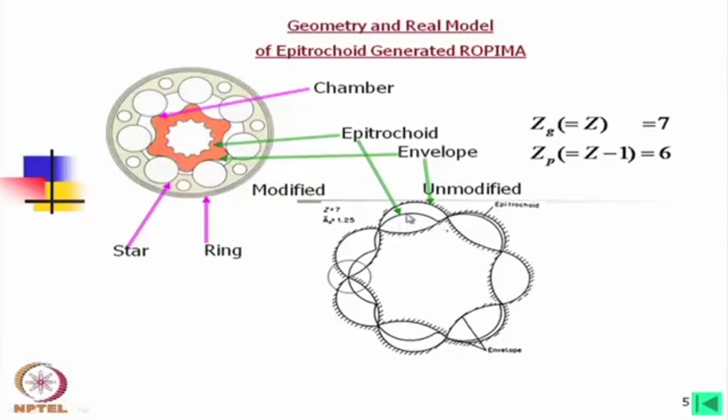How? If we make this one a solid cutter, then we will find it will make a profile like this, which is actually the envelope. Motion is the same as what you have just seen. Or if we make this a hollow cutter, do you understand? So, let us consider a cylindrical body and the inside shape is like that, this portion is hollow. In that case, this will generate a profile like this.